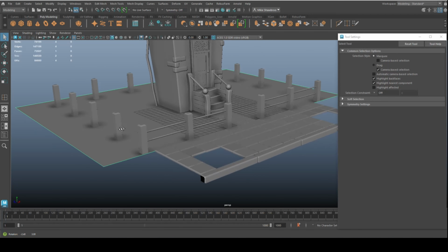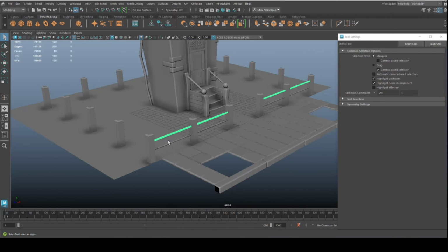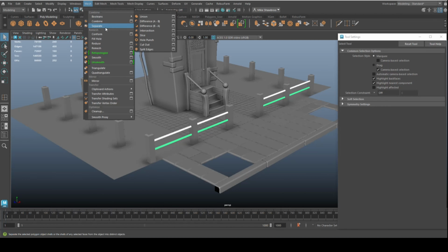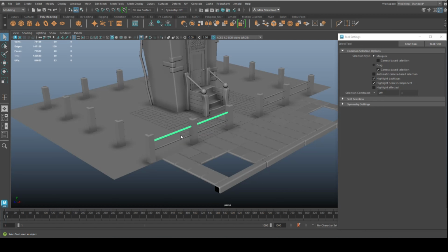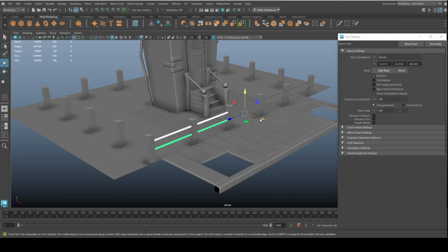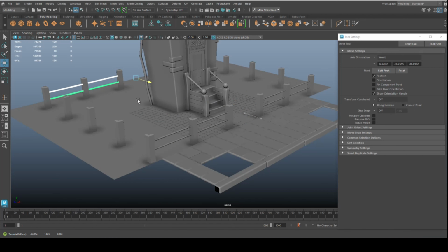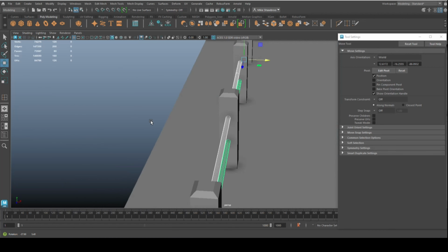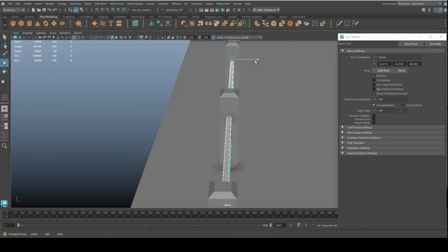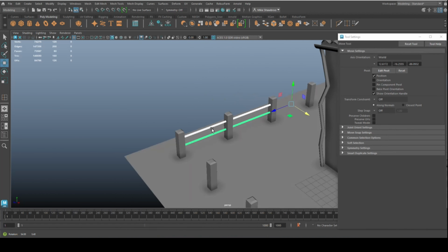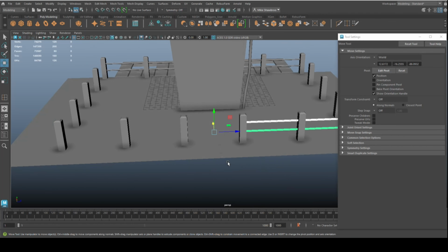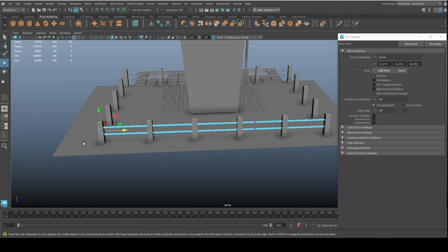Right, now we need that all the way around. So let's take these 2, and we're going to go to mesh and separate. Okay, Control D to duplicate, W to move back. After frame, this is in the middle. It's pretty good. And now, of course, we can go in here, right click, go to vertex, drag select these, and pull them to the end.